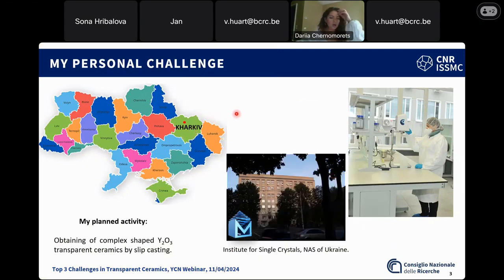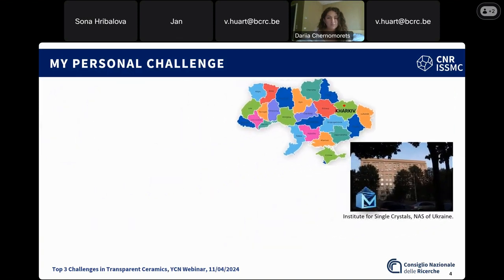There are two viscosity flow curves of yttria-based inks with different solid loading, and in general it's more or less the same, with a difference of only 6% of powder, but viscosity changes really significantly.